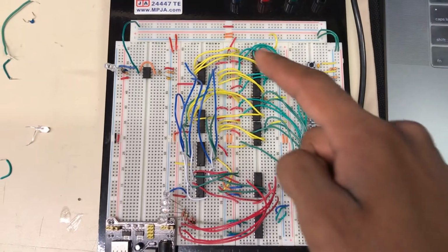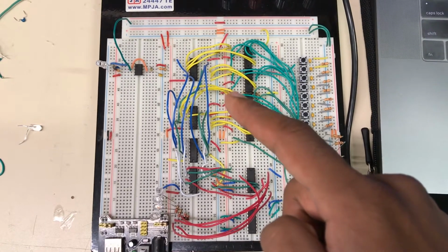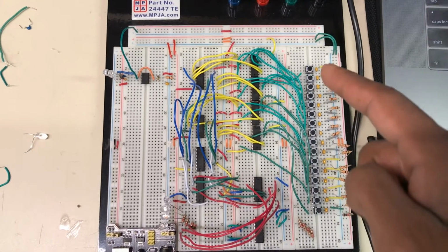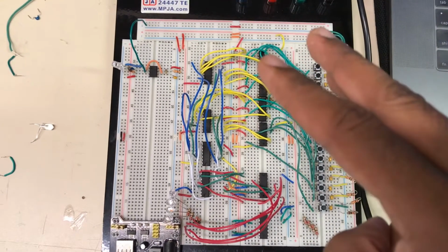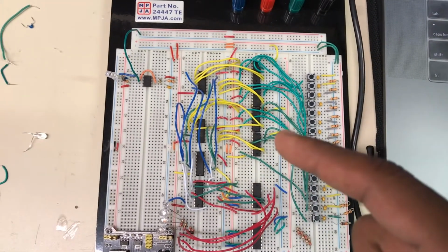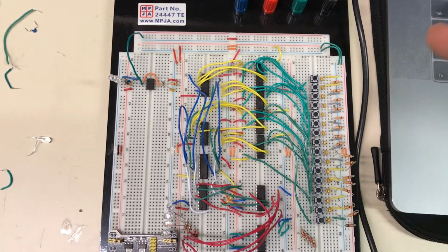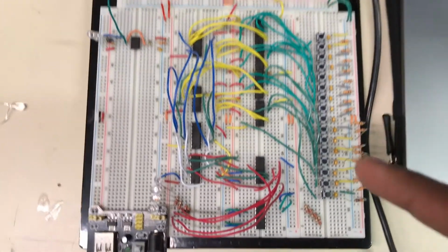And then the output from these registers are sent into 2 priority encoders. The purpose of the encoders is they can represent these 8 data lines at a time as 3 outputs. And so when you combine 2 of them and cascade them according to the schematic we have, you can create a 4-bit representation of 16 lines of data.